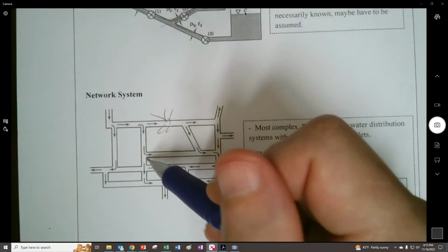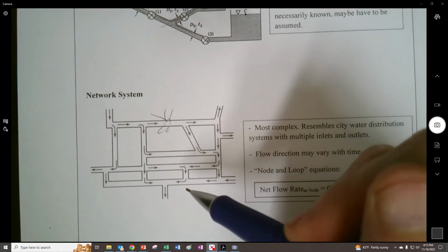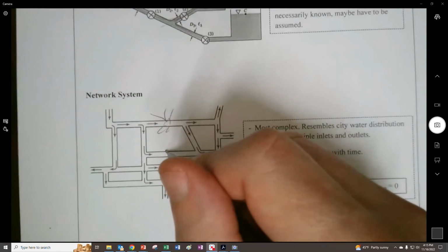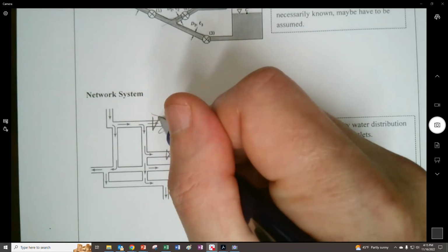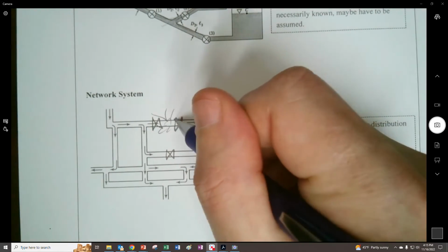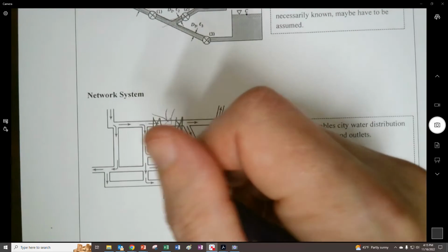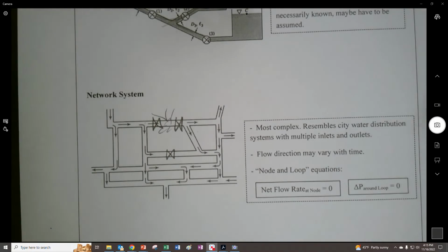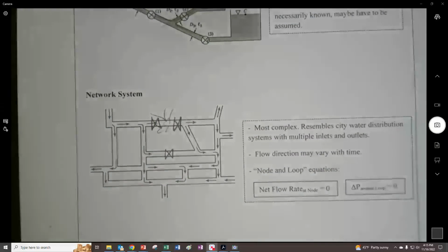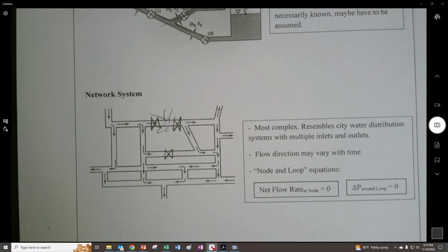You want to have a different route to come through. Maybe you accomplish that by having valves that are shut, and ways to isolate this section off. So you could shut these valves and then open up this one so you can continue to the other fire hydrants. But this is something that can occur in other situations.